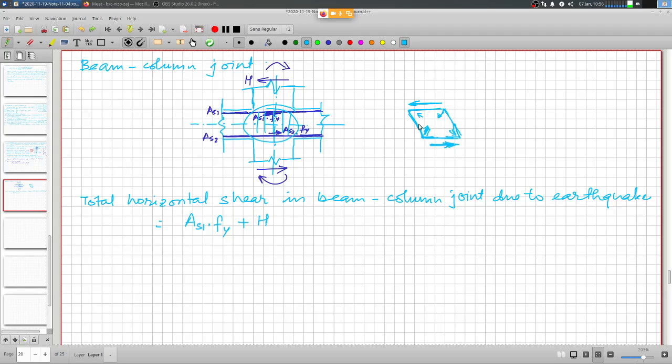See, steel being a ductile material isn't helpful if the structural behavior as a whole is not properly designed to control the behavior as we want it to behave. For example, we don't want this panel zone to buckle in the event of seismic loading.